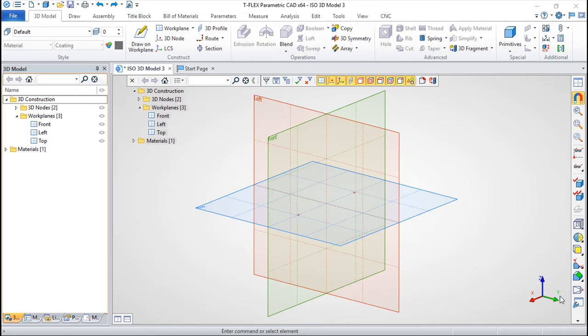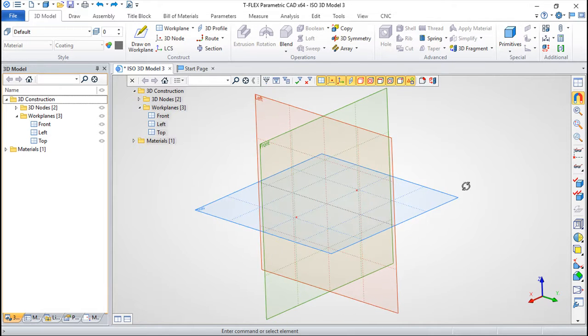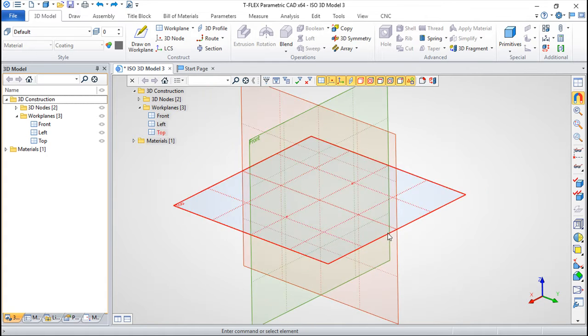Hello, we are here for one more lesson of this T-Flex CAD training course, and the topic for today will be the springs. The operation spring creates a 3D body as a conic or cylindrical helix-shaped spring with a round profile. This body is created by sweeping a circular profile along a helical curve defining the spring trajectory. It seems very complex, but in fact it's very simple.